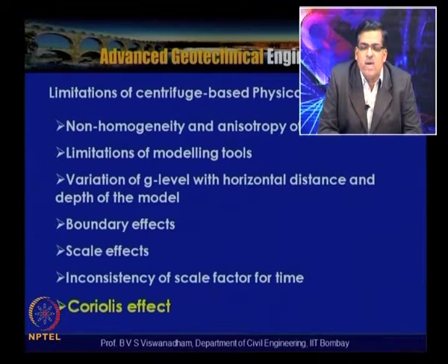In case we have highly plastic soils, this needs to be arrested by lubricating the inner sides of the containers, so that the boundary effects are minimized, due to adhesion in case of clays, and in case of sandy soils due to friction between the wall and the sand grains.